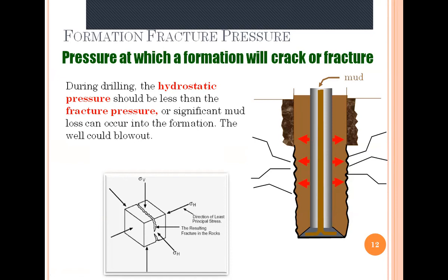And you know, there is a test we are doing for the exploration well. We are doing something called the leak-off test, the LOT, where you start closing your well and you pump quarter barrel by quarter barrel until you see a pressure reduction or pressure leak, and this is your frac point or fracture pressure. And in the development well, you just make something called FIT, which is the formation integrity test, just to test that your hydrostatic pressure will not cause any problem to this formation.